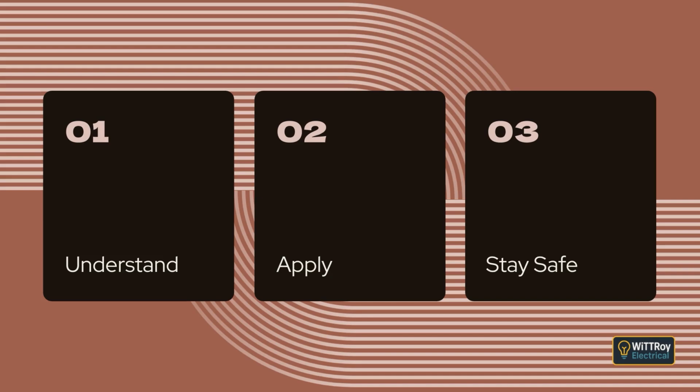Where these devices are installed, they must limit the overvoltage to a safe level below the insulation rating of the equipment, operate at voltages appropriate for normal conditions, and not cause hazards to people or animals during operation. This clause also explains that the standard does not force every installation to have surge protection. Instead, Appendix F gives guidance on when surge protection may be appropriate and how it should be selected.